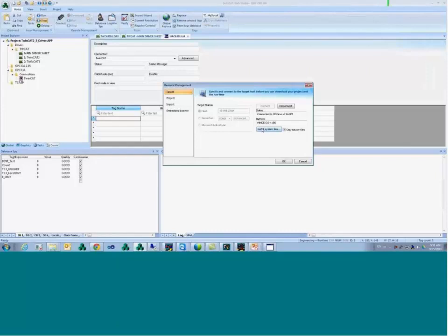After you run install system files, you can even delete the DRV folder that we installed there. Keep only the bin folder. That's the easiest way to have the Beckhoff device as a web thin client or as a secure viewer. Just run install system files. It installs everything you need. Okay? That's the question on how to have a web thin client on the Beckhoff device. Copy the CE server file there, run it, and install system files.